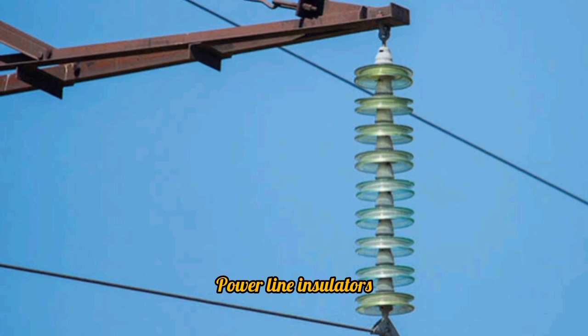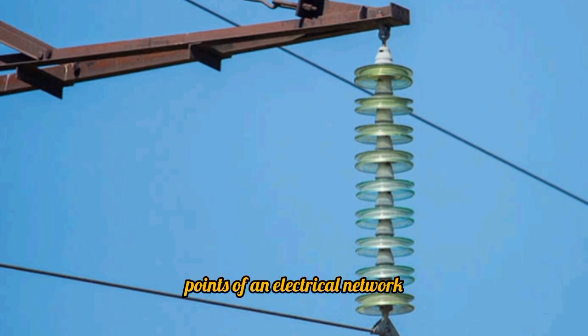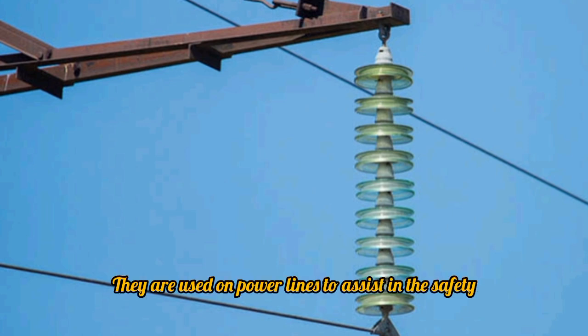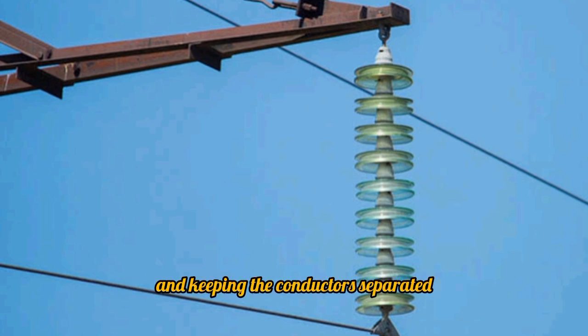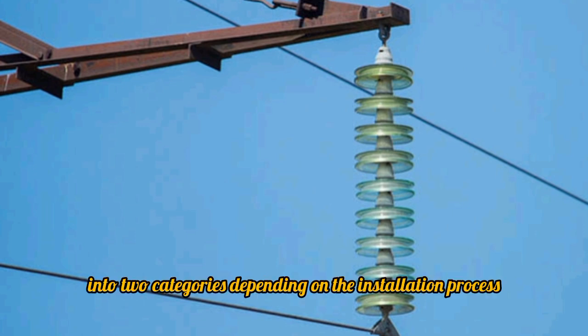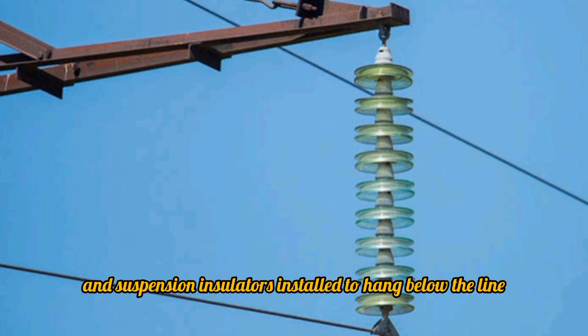Power line insulators. Insulators restrict the power flow at defined points of an electrical network. They are used on power lines to assist in the safety and support of the structure by reinforcing the line and keeping the conductors separated. Power line insulators can be loosely split into two categories depending on the installation process: pin insulators, installed above the line, and suspension insulators, installed to hang below the line.